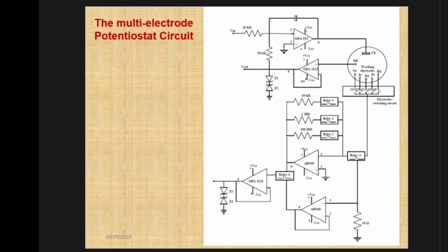So we are actually trying to support measurement of current from nanoampere up to milliampere level. So we are using 1 megaohm, 100 megaohm, so pretty big resistances right now, buffered output stage, and they again go to the analog to digital converters. So we are using an electrochemical grade operational amplifier, AD549. This has a very low input offset current in the order of picoamperes. Our measurement range is in nanoamperes, so it should not create problems.